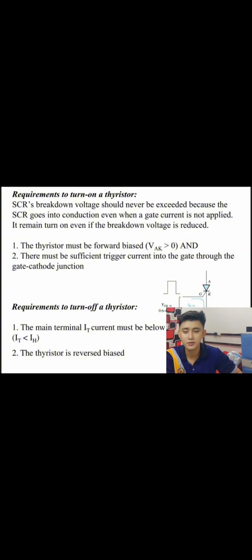Requirements to turn off a thyristor. The main terminal current IT must be below the holding current IH. The thyristor is reverse biased. So, next slide.